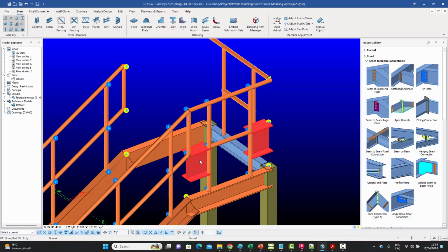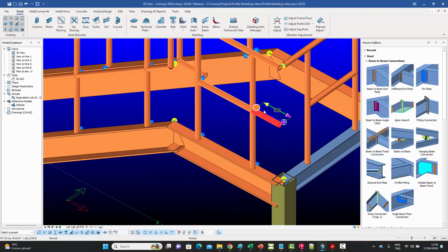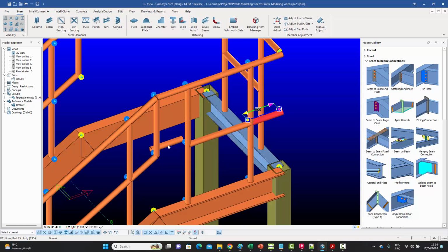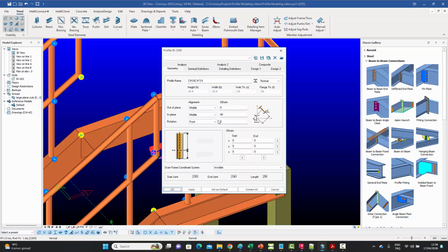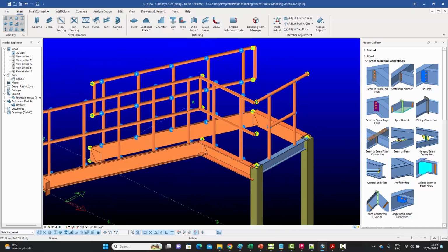Just select them, right click, say match elements with this one. And okay, some of them don't work all the time because of the opposite direction. So what you would need to do is click on that. This happened because of the order in which we chose the points. So there we go. We can correct that very easily.